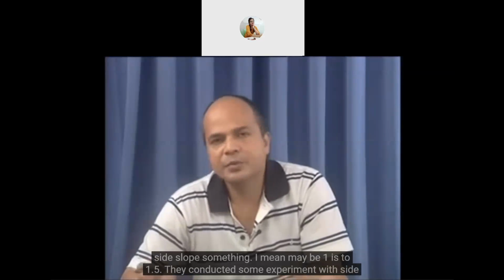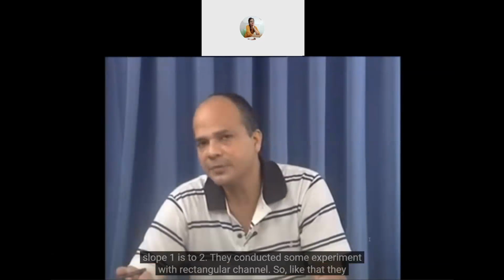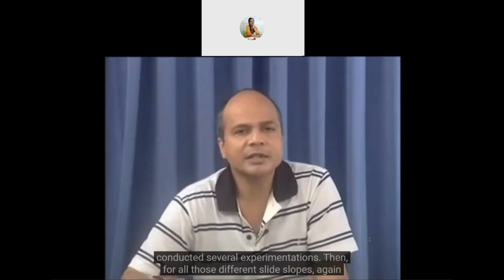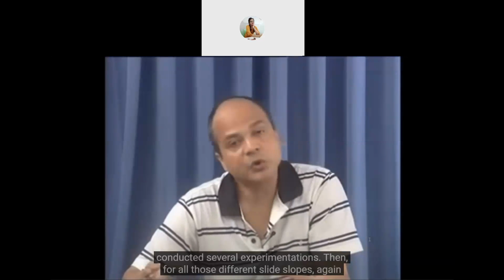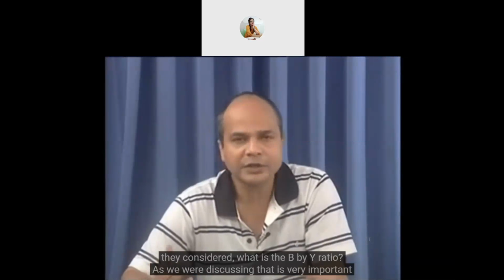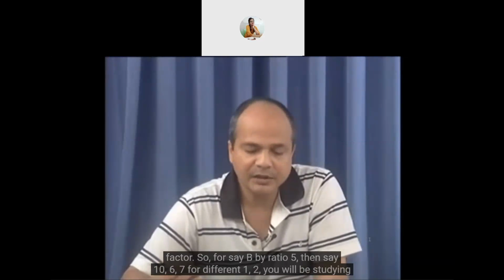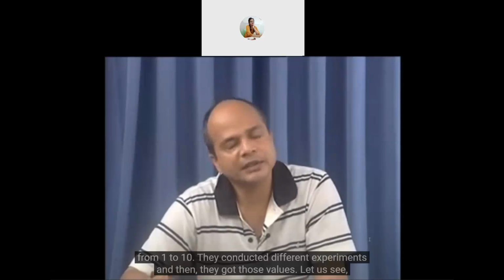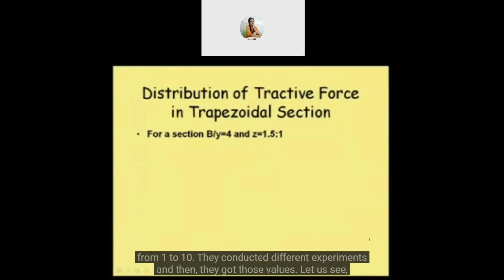With side slope 1:2, they conducted some experiment. With rectangular channel, they conducted some experiment. So like that, they conducted several experimentation. And then for all those different side slopes, again, they considered the B by Y ratio. As we were discussing, that is a very, very important factor. So for B by Y ratio 5, then 10, 6, 7, for different side slopes, even starting from 1 to 10, they conducted different experiments. And then they got those values, and let us see how these variations occur.